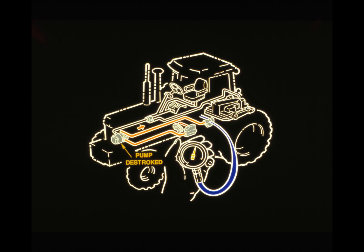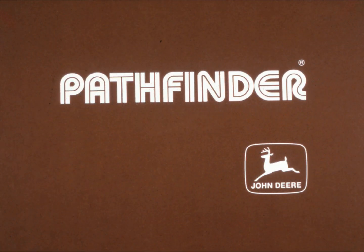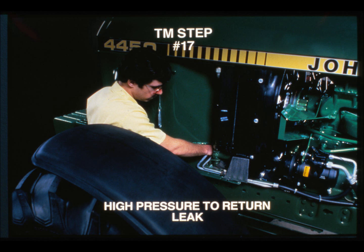Now turn to the next step, number 17. Press restart when you're ready to continue. Step number 17, checking for high pressure leaks to return, also involves destroking the main hydraulic pump.